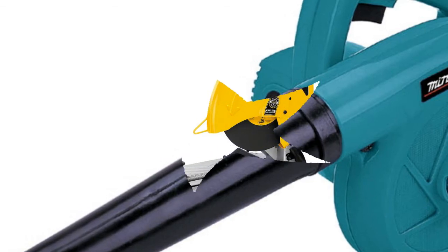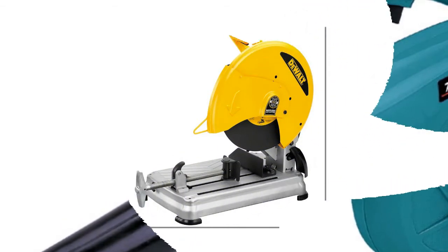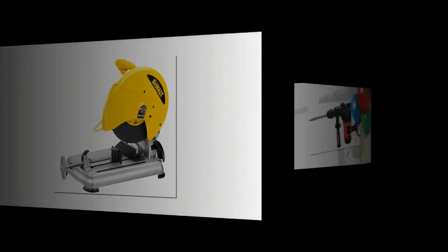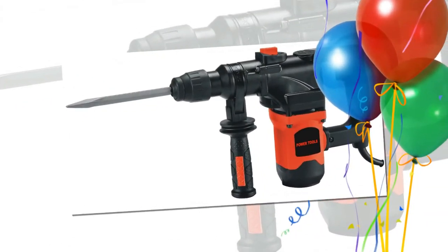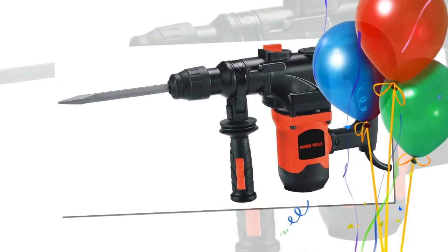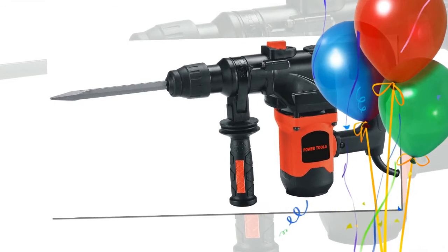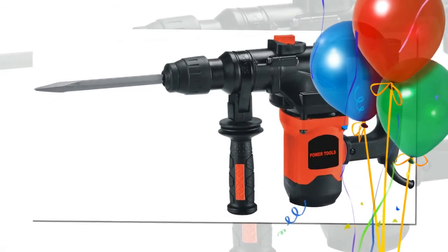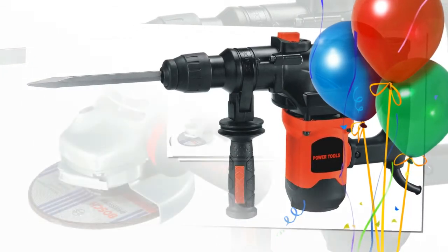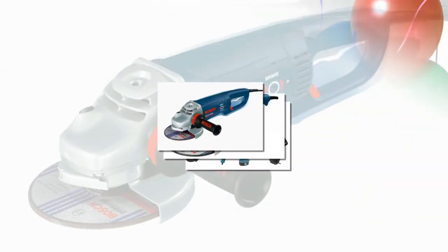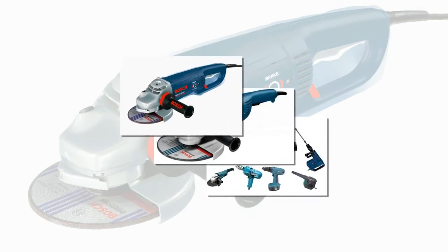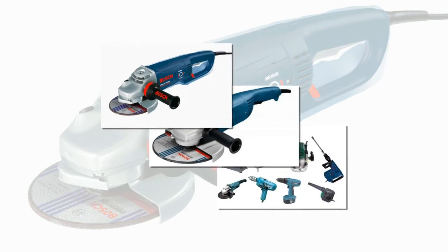Power tools usually come in one of two categories, stationary or portable. Stationary power tools are either large machines that are not easily moved or machines that must be tightly fastened to a stationary object in order to properly function. Portable power tools can be easily carried from one location to another, and are usually light enough to be used while being held in a person's hands. Stationary models usually have the advantages of precision, power, and smoothness. Portable versions, of versatility and travel.